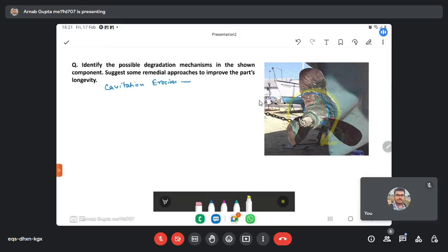So as a result of which there will be regions of low and high pressure. Near the propeller blades, there will be some low pressure region. So there the liquid phase turns into a gaseous phase, vapor phase. So you will see bubbles forming within that stream of liquid which the ship is propelling. So this is your propeller, say, and it's moving in this direction.